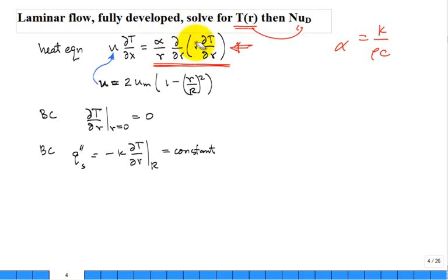Okay, then I look over here. Well, this alpha, I put that rho C back over here. What's that look like? On the left-hand side, advective transport of energy. So if I take this control volume and shrink it down to an itty-bitty small point, then I get a differential equation. This is really a heat equation. It's an energy balance statement on a point, not a volume.